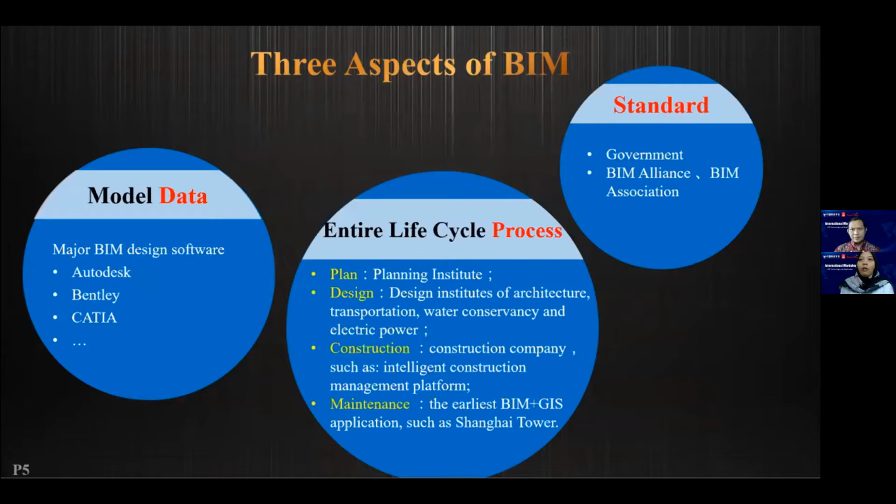stage. And if that's the case, we also should know that the deficiency of BIM applications also brings up some issues. The first issue, there are many kinds of BIM modeling software which have inconsistent data formats. The second issue, BIM only focuses on the management of the whole life cycle of the building, but lacks the surrounding macro-geographical environment. And the last issue, BIM only focuses on design and construction, but it lacks later operations, maintenance, and also management. We will discuss these issues one by one on the following slides.